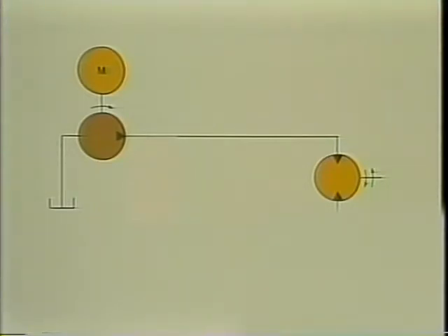Now, with an electric motor driving our pump, let's see what happens with our hydraulic motor. Since it's a positive displacement unit, if it were to stall, it could not accept any more oil. The pump, also positive displacement, would stall too, since its outlet would be blocked. This, in turn, would stall our electric motor.